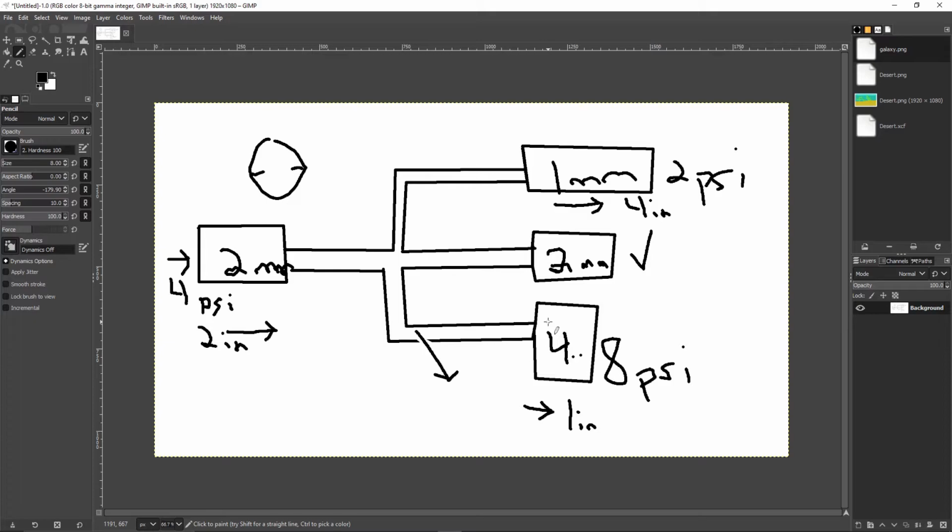So you could say, hey Bill, come step on this clutch pedal for me. Or really grab a porter. Travis, come step on this clutch pedal. And while he steps on it, you can take your flashlight and look at where the slave cylinder is mounted on the side of the transmission and see it moving, and you go, oh yeah, it's definitely not that. Or, hey, this thing isn't moving at all. Alright, well, the way I'm going to go about diagnosing this is completely different.